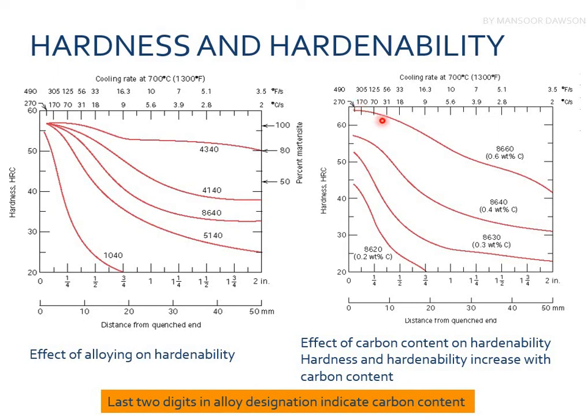You should also remember that as the percentage of carbon increases, up to a threshold, not increasing all the time, the hardness values also increase. So the effect of carbon content on hardenability: hardness and hardenability increase with the carbon content.